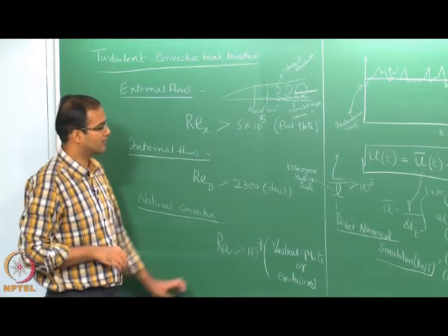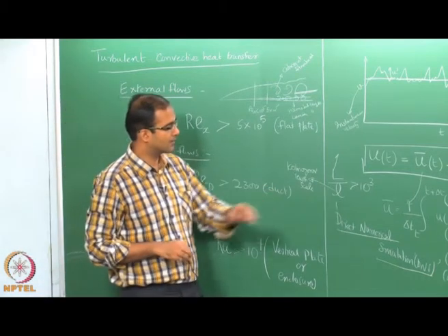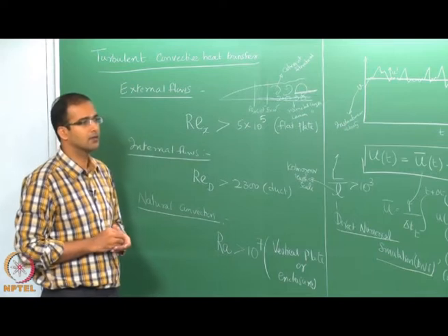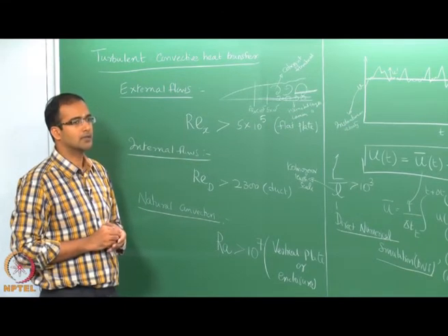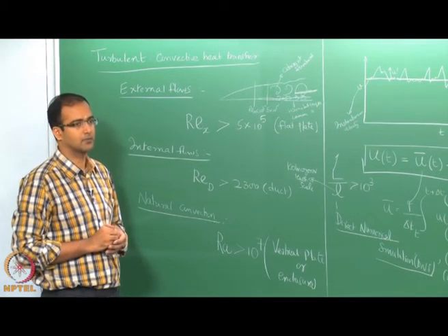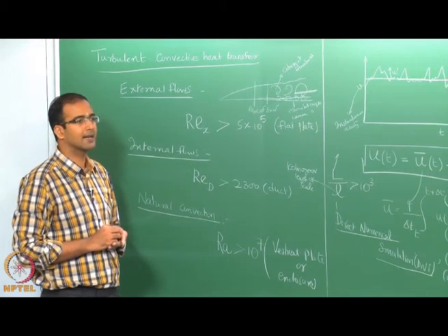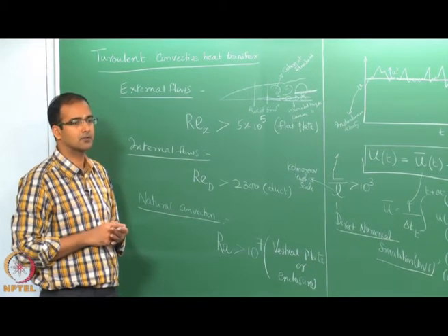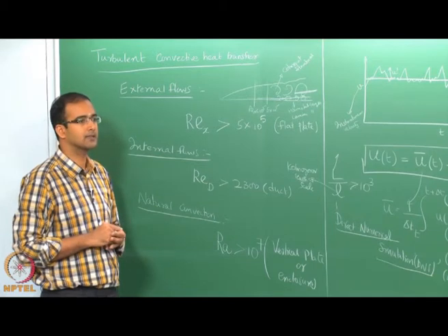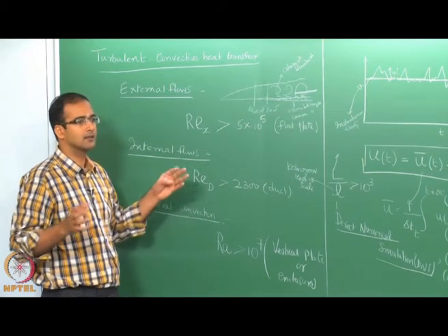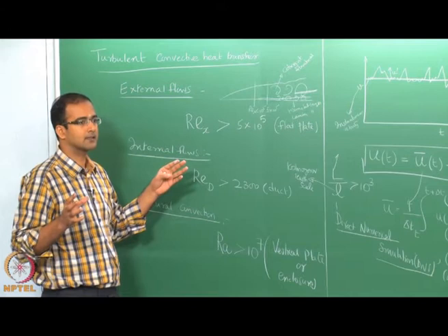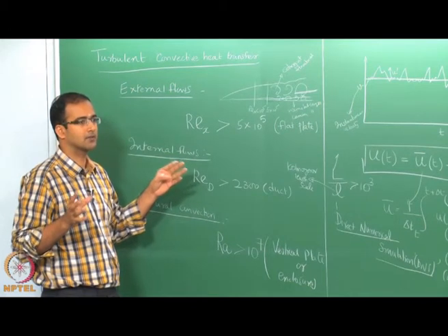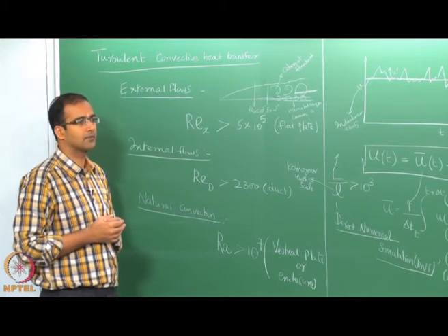Okay. So, therefore, this is called the Kolmogorov length scale, and if you plot what is called the energy spectrum. So, usually when you are doing a DNS, the first thing that you are asked to show is the energy spectrum. That means it tells you how many turbulent length scales, turbulent energy scales, have you resolved with your grid.